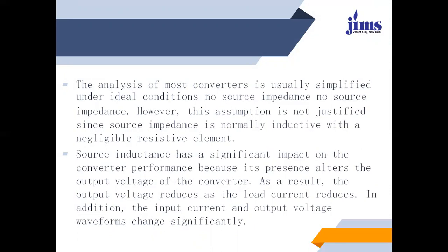The transformer which we use to deliver the supply to the consumer also has windings, so there is source inductance. There will be a transmission line, which also includes resistance and inductance. Every wire we use has some resistance and inductance. So the source inductance is an important parameter when we look at power electronics controllers, especially in the design of rectifiers.